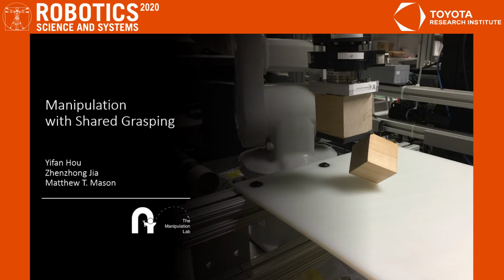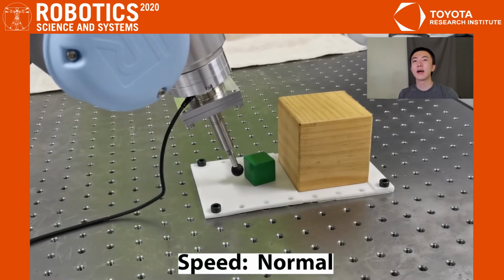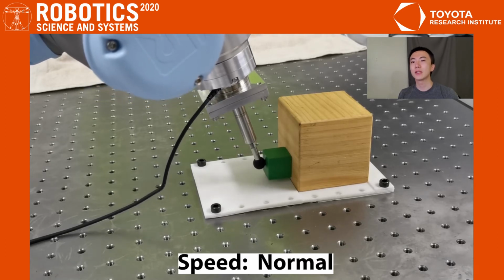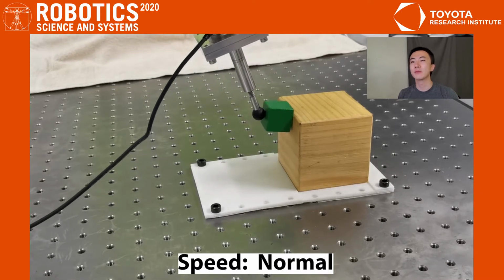Today I'm going to introduce our work on manipulation with shared grasping. Shared grasping is a grasping on an object formed by contact with both the robot and the environment. Comparing with grasping, shared grasping requires less contact points from the robot hand, so we can use it when a good grasp is not available.